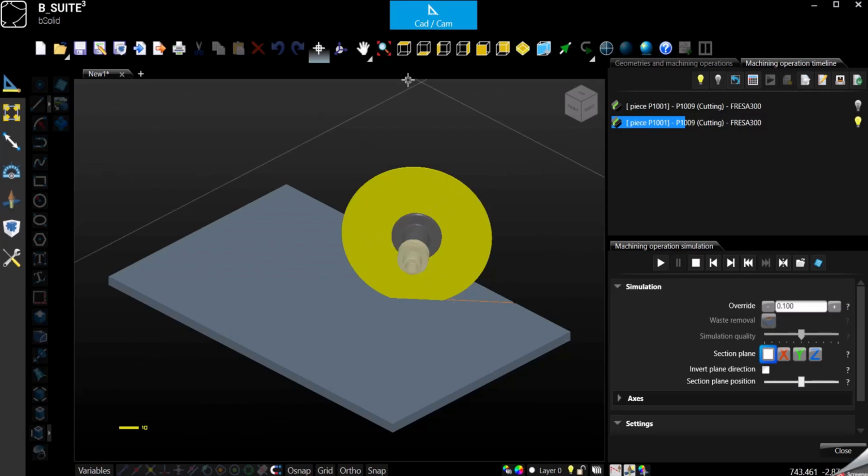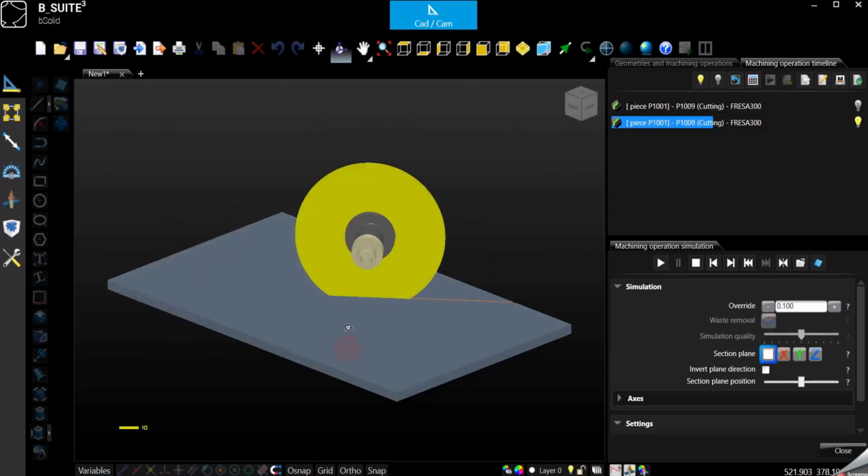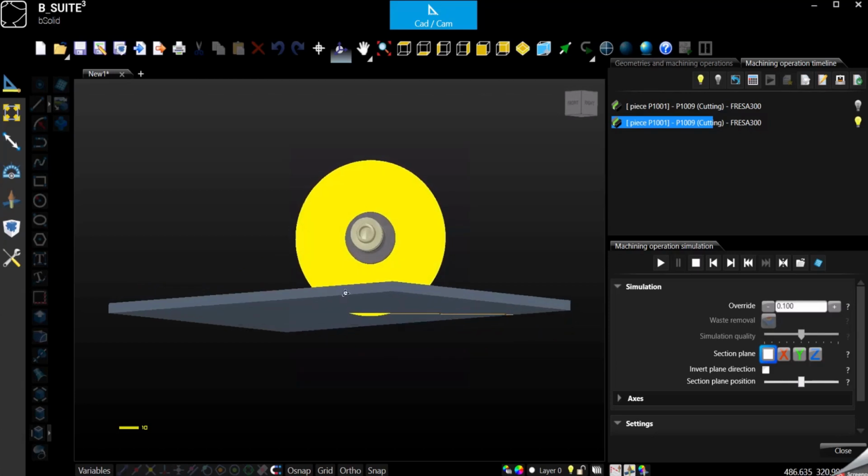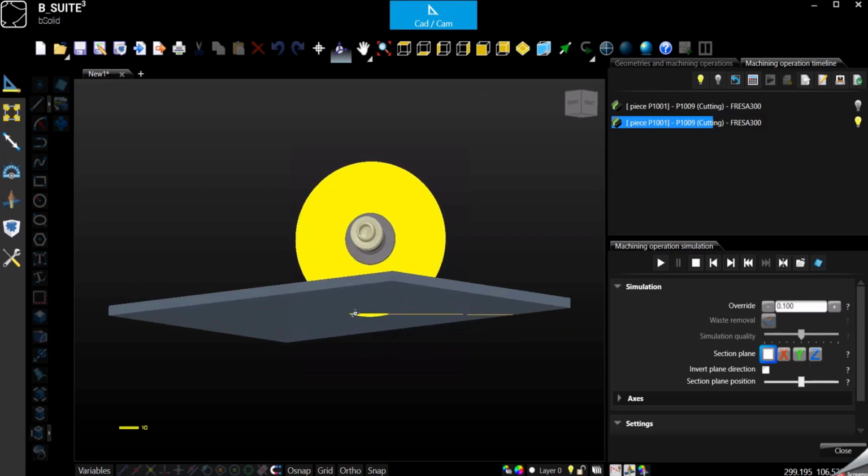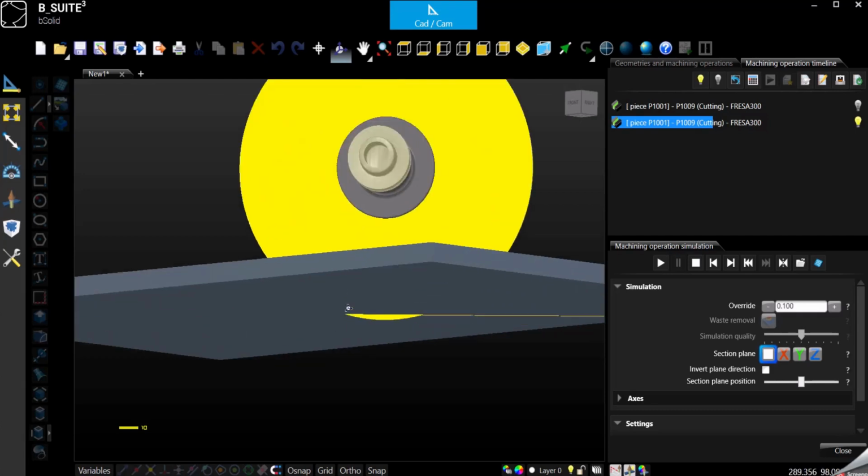But since it is a through cut, of course the teeth at the bottom of the panel will still be pushing down, and so will chip the bottom of my panel.